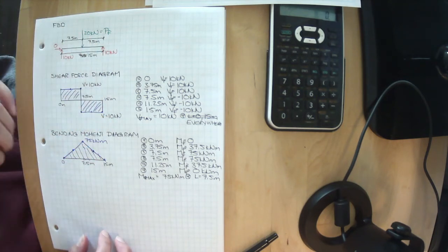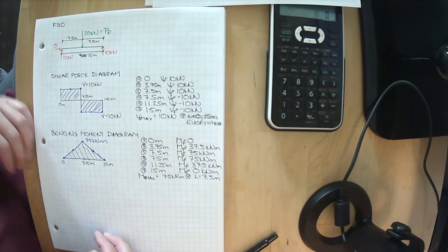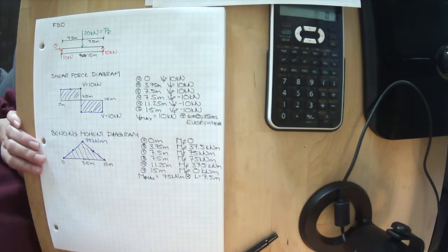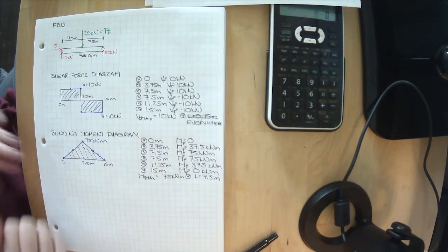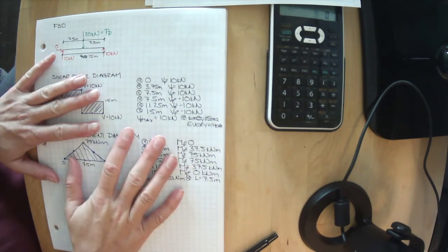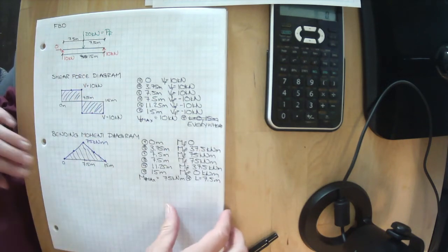We have now solved the one side of our equation, the load side of our equation. Remember, the reduced capacity needed to be greater than the factored load. We have now solved for internal factored loads. We can start to move on to the next part. But don't worry, we're going to do a few more examples like this, so you're not left trying to figure out what the heck I am talking about.